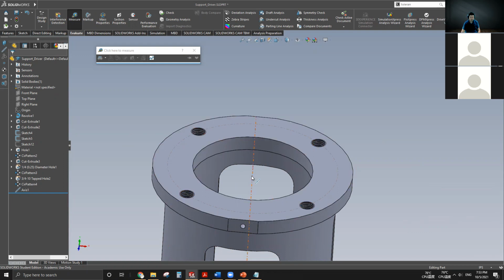And without this as a reference, the drawing states these holes will lie in a circular pattern that is 8 inches in diameter. Without this as an origin, you can have the circular pattern right here or right here, right? Kind of the same deal as this plate moving freely.